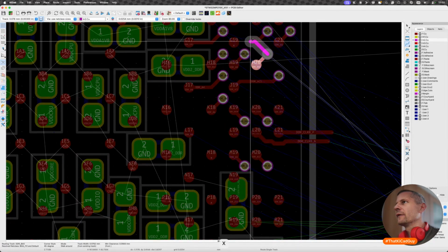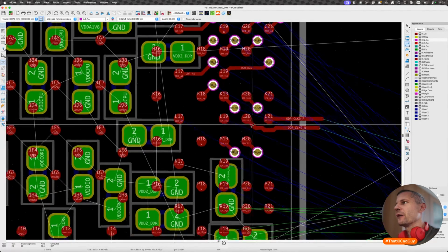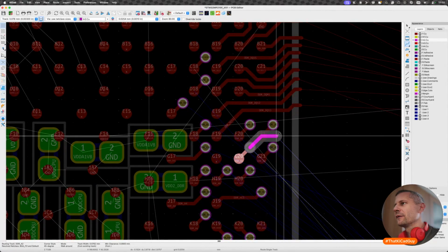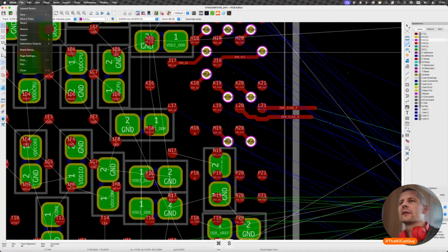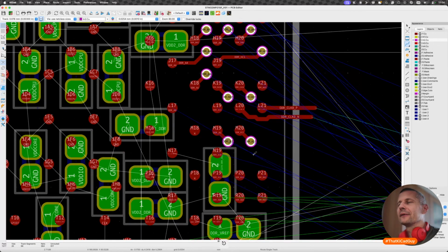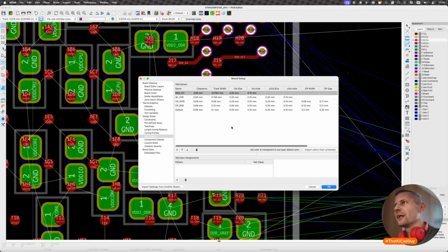Yeah, and see that there are still clearances, and you must be careful. What's good is that we can easily go in between vias in all directions. So it means it's correctly chosen. I mean, the manufacturer wouldn't complain, but it means that all the limits are set so that we can comfortably route the tracks.